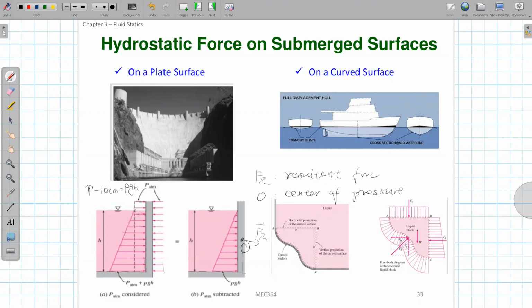That is this length, and after you go into the water, you have the additional length here, and here, due to this rho g h, because h is going deeper, making the pressure force bigger. So that's why you see this triangle form to make it larger.